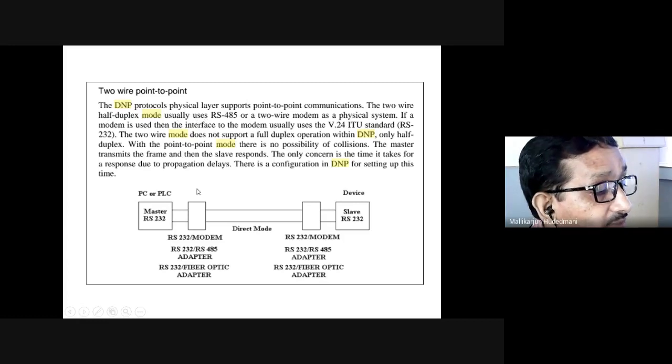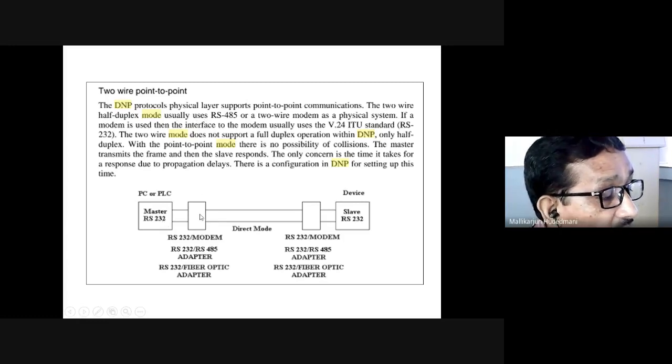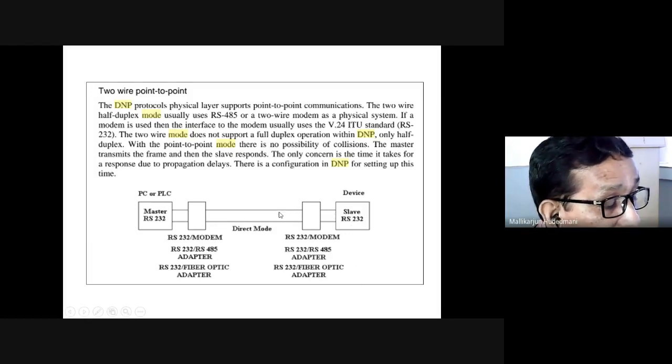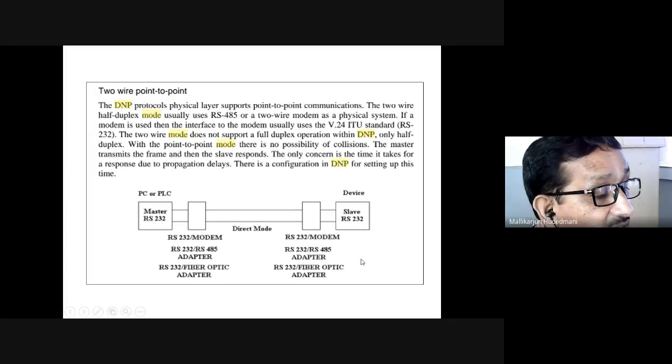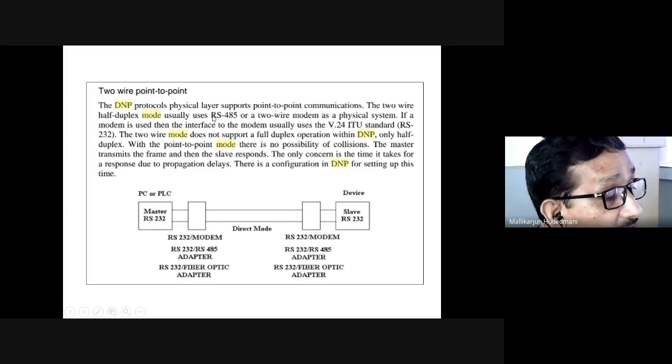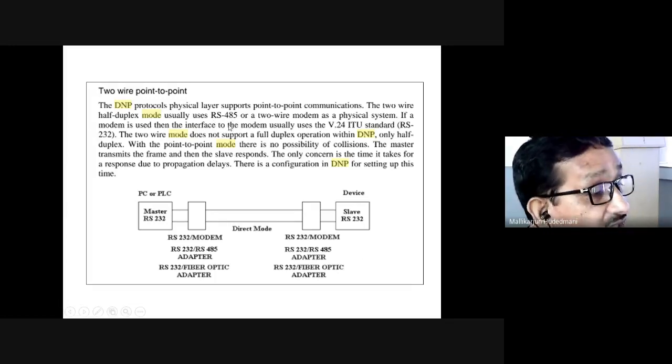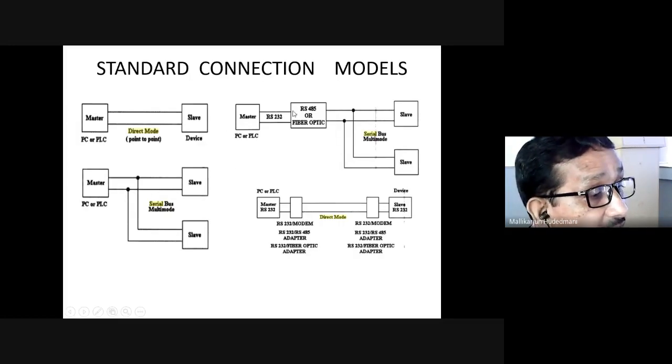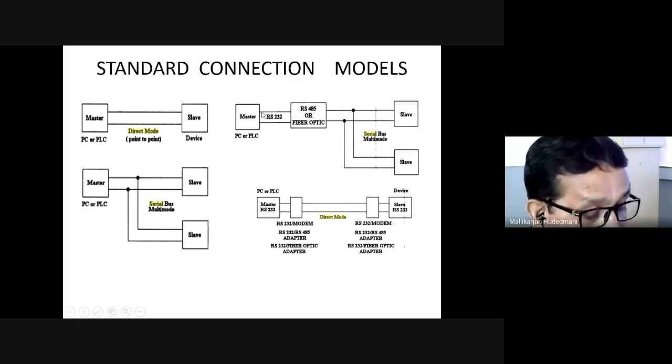Usually it is either RS232 or RS485. Suppose I have one device, it is like this. Suppose I have multiple devices down the line. I can switch to the second device, third device. Then I must be using the RS485 switcher, which you have shown me. The RS485 switcher will divide into 1, 2, 3, 4. It is responsible to send the information to the respective device only and get the information from the respective device only. That's what is shown here.